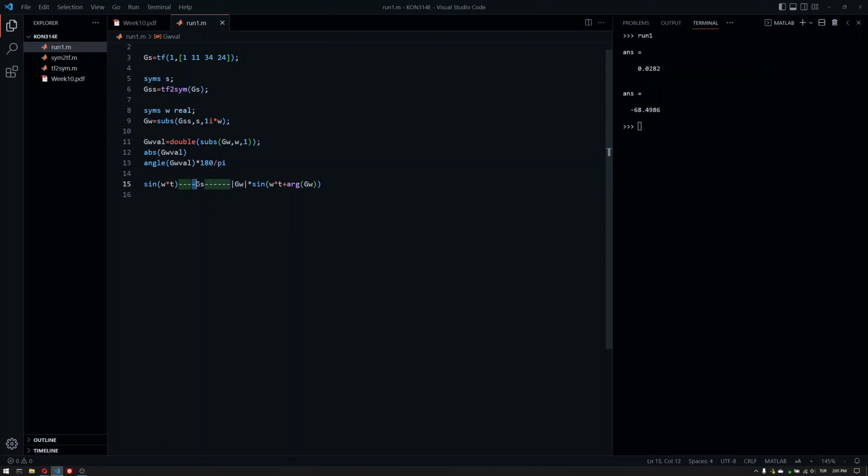So then you can combine the frequencies and see that the transfer function will shape the output here. Since the input will be in terms of sine waves, the output will also be in terms of sine waves. For each frequency, it will have gain and phase. You can then go ahead and calculate your output basically.